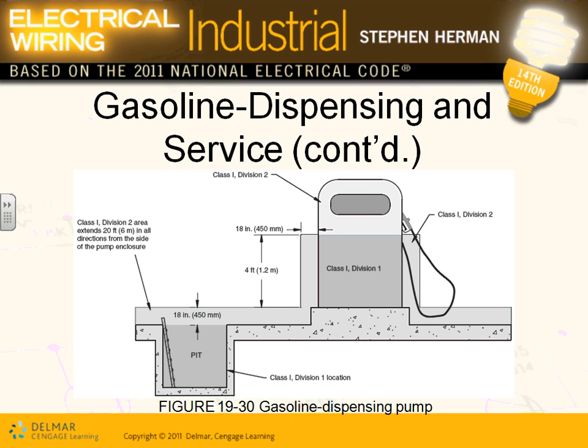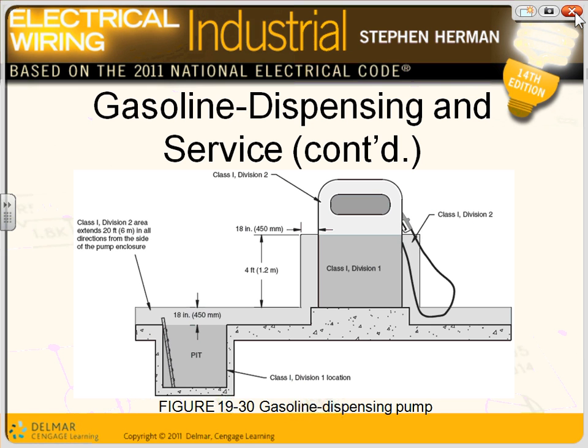Here's where you go fill your car. When you go fill your car, guys, any pit in the area is always classified. Any pit in any location, for the most part, is a Class 1 Div 1 location in these areas. Now we have gasoline here. This is Class 1 Div 1. What they do around the gas pump, 20 feet in every direction from the pump, and 18 feet above the ground, is classified as Class 1 Div 2.